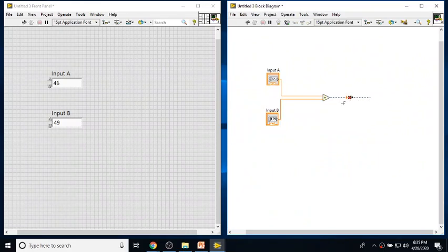The reason why this wire is broken is that it was connecting a source and a destination, whatever it is, right? So it was connecting two items, but now one of the items is missing. So this wire is now floating, right? You're supposed to remove this. When you have a broken wire on your screen, you can see your run button is broken. It means that you cannot execute your application. Your application has an error.